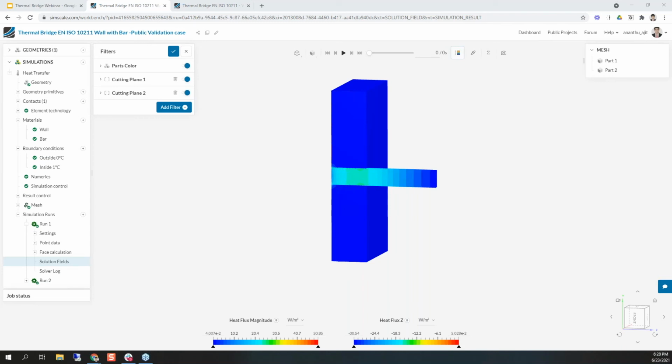Ricard, you wanted to add some detail to the second part of the question. Yes. Taking into account cavities, I think there are many methods for how this can be done. Traditionally, for FEA-based software, you use a simplification of the cavities based on rectangular patterns, and then you take a fake material based on the size of these cavities. That's one option that you can also do on SimScale. What we don't have is an automatic way to define something as a cavity and then automatically compute this surrogate material properties from that. You will need to do that manually.